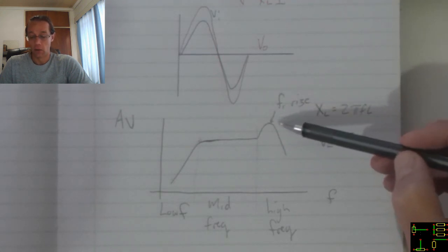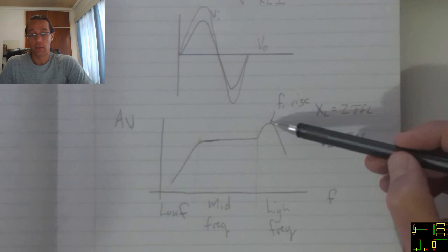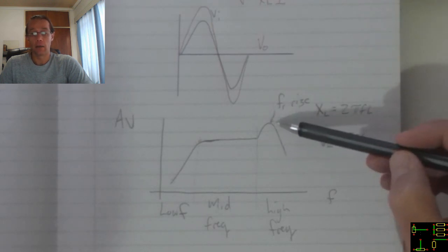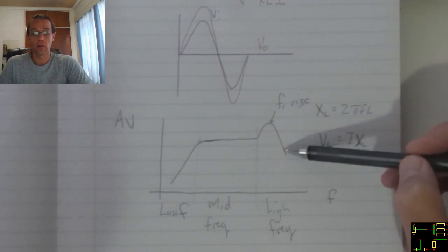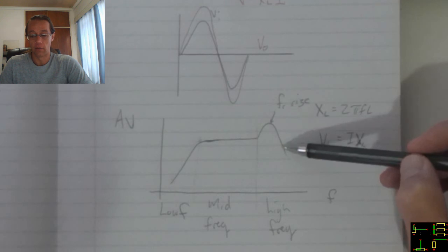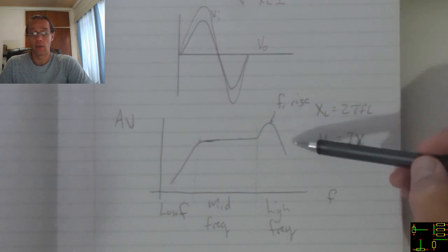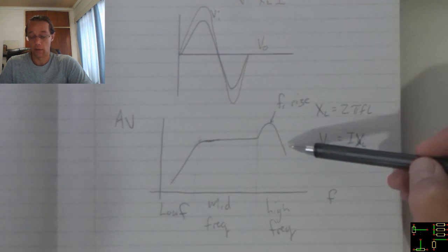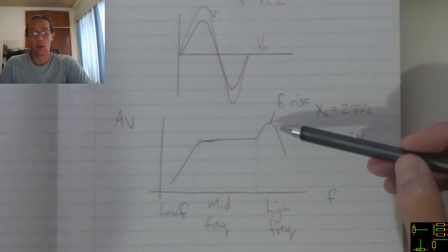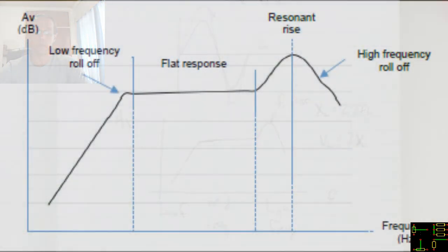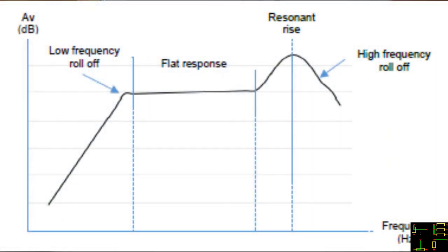Because of that capacitance, it forms a low impedance path for current to flow through the capacitance, which is created by the high frequency, instead of through the coil. And as a result, my output gain will greatly diminish.